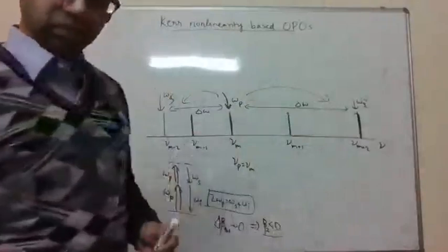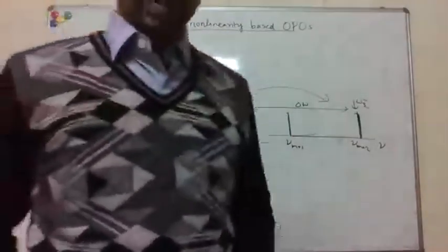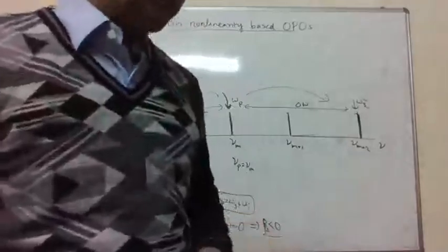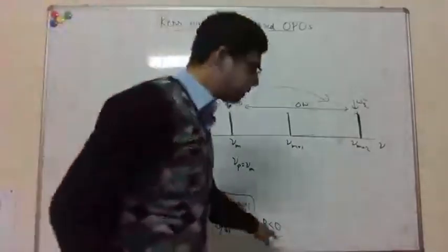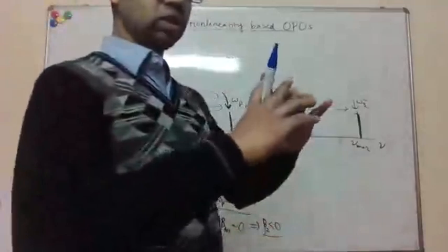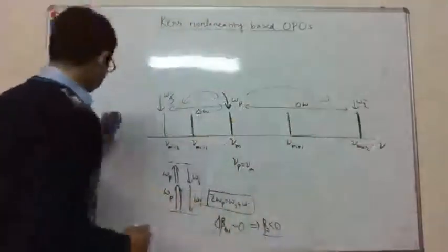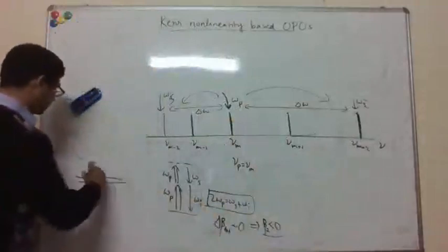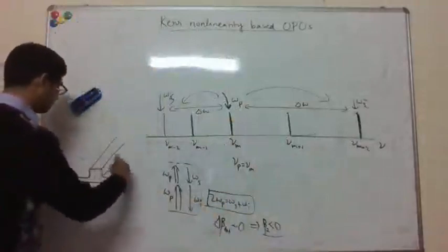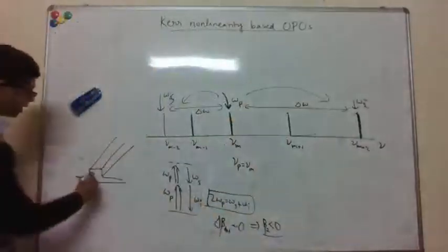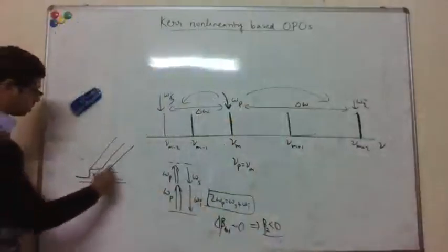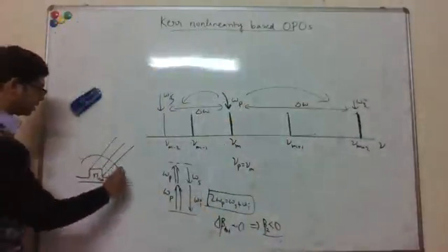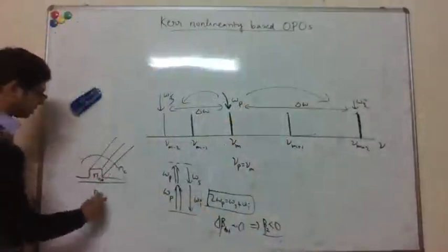Is it possible to get the anomalous behavior in a ring resonator also? Yeah. So this anomalous dispersion is a property of the waveguide, right? Typically, you have some cross section of the waveguide, so you have some core material, then some cladding, and some substrate.